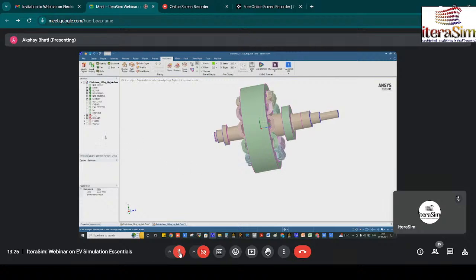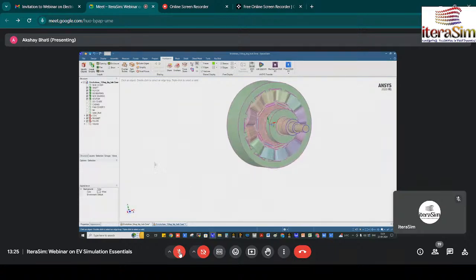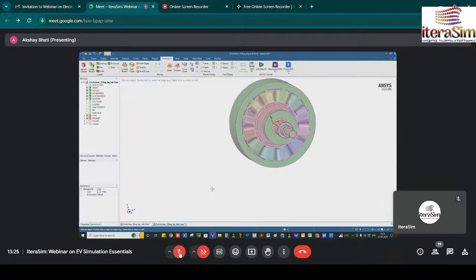Okay, after that, here is one more thing I want to show, that is the filler. If you minimize the filler, you see there is a gap. Basically, the winding doesn't contact directly any part of the stator, otherwise electric current leakage will occur, and the whole casing and every part will have some electricity.